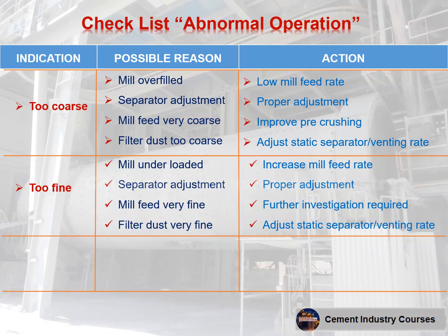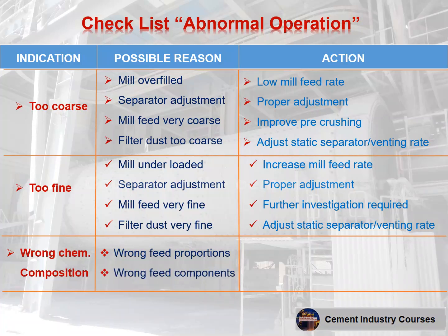Indication: wrong chemical composition. Possible reasons: wrong feed proportions, wrong feed components. Action: adjust proper proportions. Change component quality.